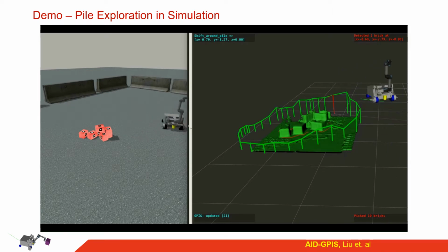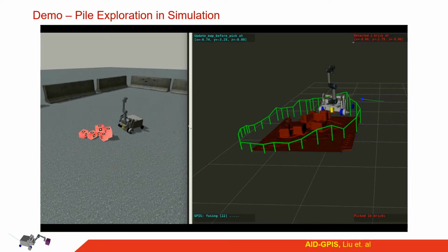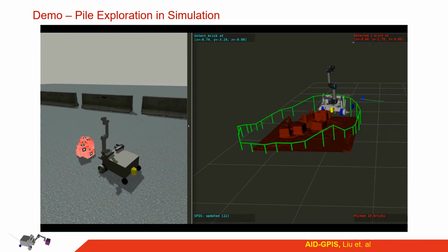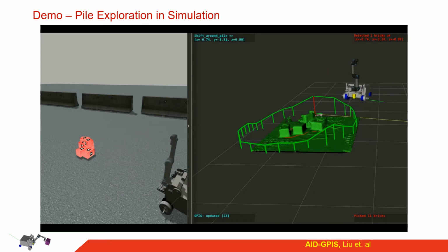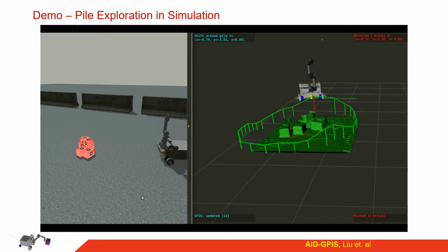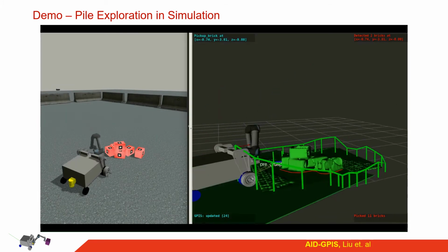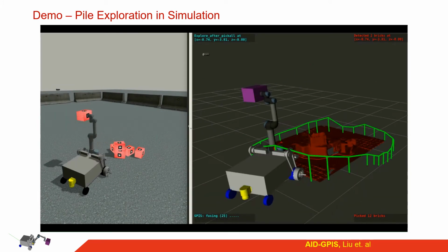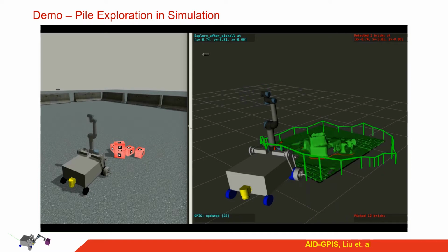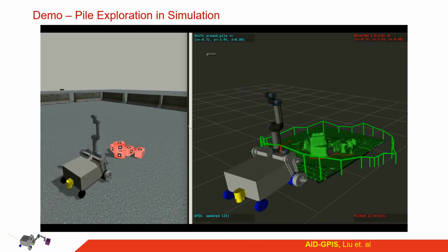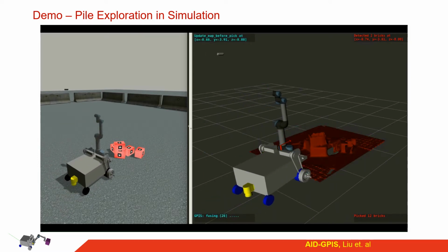For the exploitation part, the NBV scheme makes use of a manipulability score, guiding the robot to choose places which host as many possible pickable objects as possible. With the help of this framework, the robot is able to efficiently pick up all objects within very short time.